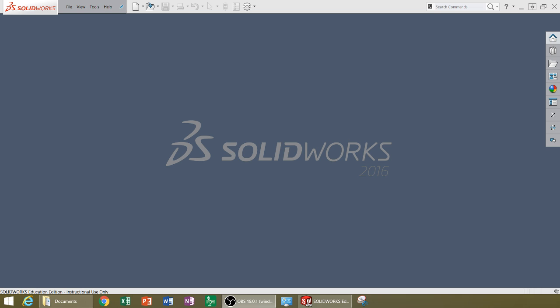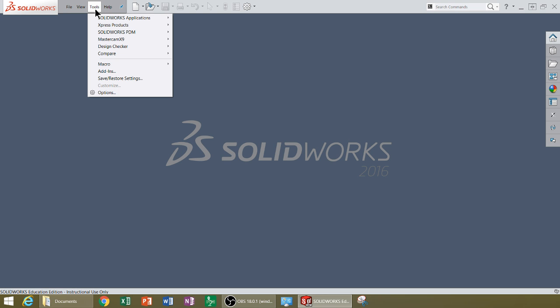Today what I'm going to show you is how to turn on the ability to auto-trace an image that you place inside of a sketch. To do that, you need to have an add-in turned on, and to find that, click on Tools, right up here on the toolbar. Tools, and then come down and select Add-ins.